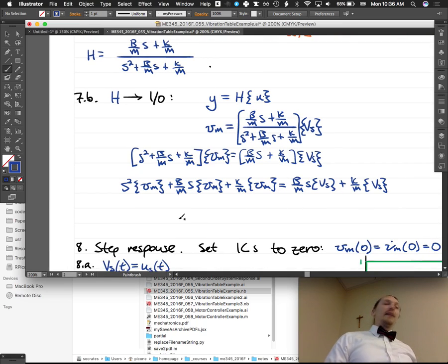And yeah, so now you can actually interpret these back to how we initially defined these operators. So S squared is what in terms of calculus operations? It's a second derivative, d squared Vm dt squared. Exactly. Or in our case, Vm double dot, the second time derivative.